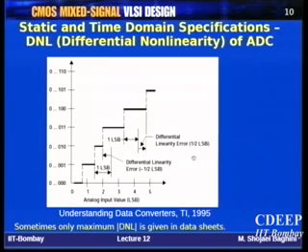Suppose you have two transition points. You expect the difference between two consecutive transition points, or two consecutive center points, to be 1 LSB. But this won't be 1 LSB. It may be less than 1 LSB, or it might be more than 1 LSB, because of change in the reference values, non-uniform offset across comparators, and offset drift with time and temperature as the ADC is working. Therefore, you may get this sort of characteristic.